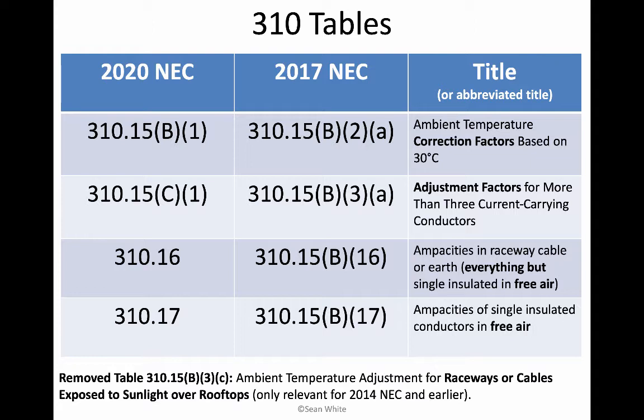There's lots of different reasons why a wire should be larger or smaller, and sometimes we're looking at Article 240 when we're sizing a wire, 250 when we're sizing a wire. So remember, 240 overcurrent protection, 250 grounding and bonding, and 310 is just our general wiring, how big that wire's got to be. But of course, there's other places in the code book that we have to look, even in Article 690, where we talk about solar.